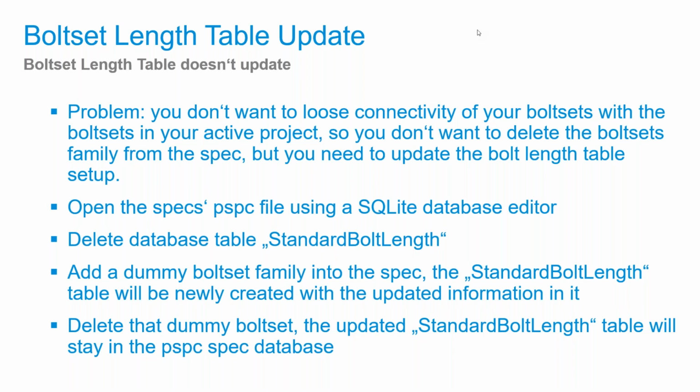It will bring the standard bolt length table again, with this dummy bolt set family, into your spec, and then you just delete this dummy bolt set family again. The standard bolt table will stay in your spec, and like this you have updated the bolt length table in your spec.